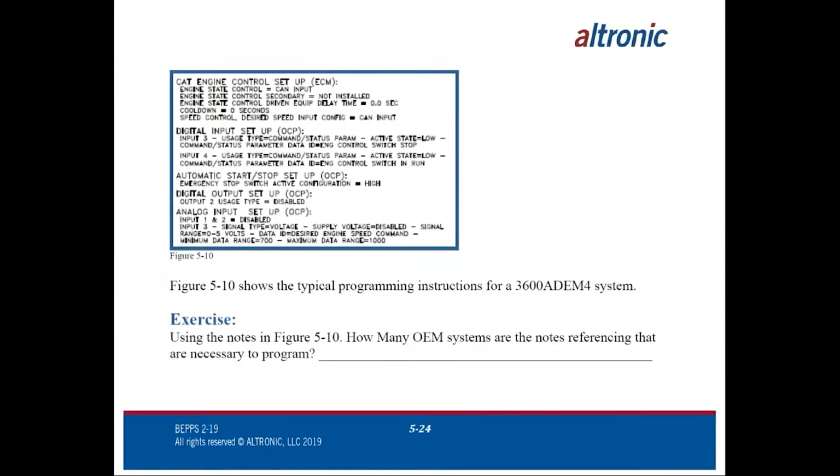And we sometimes find flaws in their systems, and we sometimes deviate in how we interface with it because of those flaws. But generally, what we try to do is follow their engine customer interface guideline. If they're talking about input 3, which can be programmed any way, we're going to say, hey, we're going to use input 3, and you must program it this way. What they don't do real well in their notations is tell you what terminal number input 3 does.